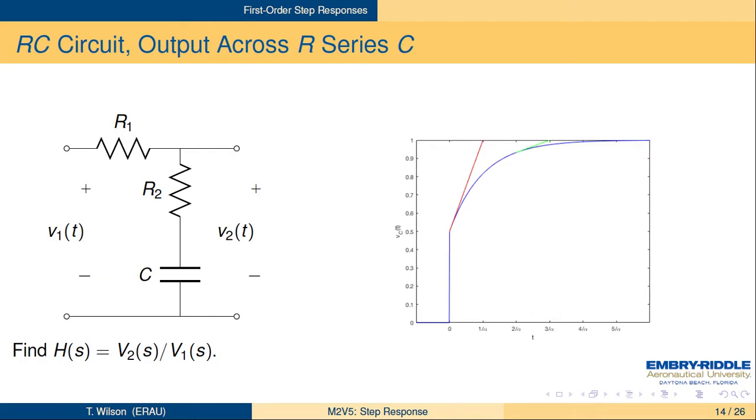So first order circuits have constant plus exponential responses. You can really figure out what the response is going to be by looking at the circuit. You ought to be able to draw the graph and then figure out the parameters for the graph without ever really having to do the Laplace transform, although it's great to be able to do the Laplace transform and show mathematically that what you intuitively have figured out is right. Alternatively, you may be thinking about doing it mathematically and then using your knowledge of circuits and the physics of circuits to understand whether the answer you get from your Laplace transform is right.